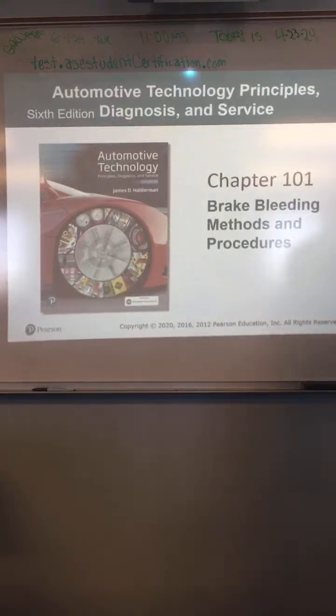Next chapter deals with brake bleeding. Before we get started on that chapter, I'm going to ask you a couple of questions. What's the purpose of brake bleeding? To get rid of the air inside of the system. Why can't you have air in the system? Because it can cause issues. It makes your brake pedal spongy, because air compresses and fluid does not.